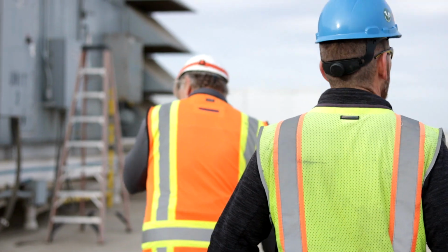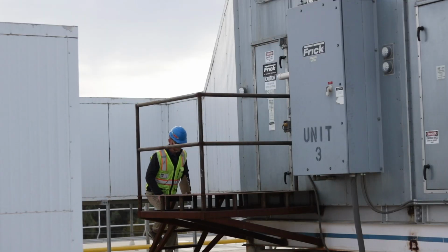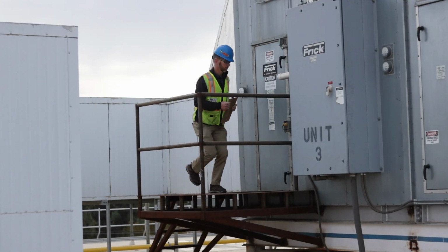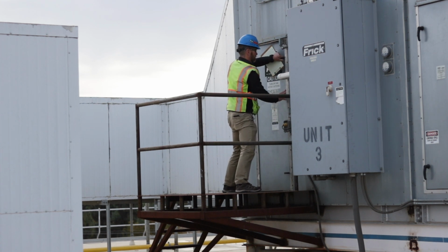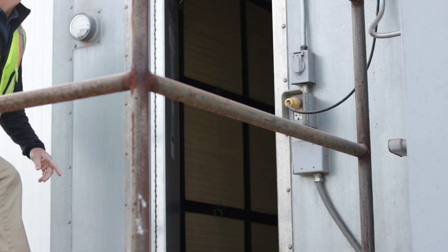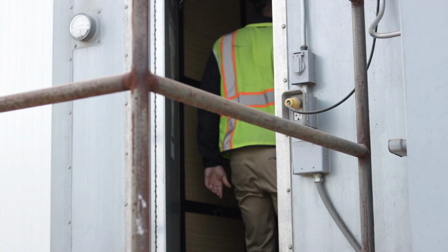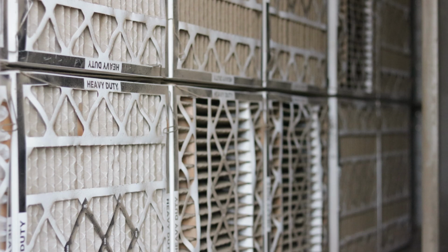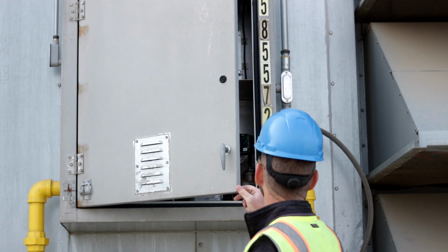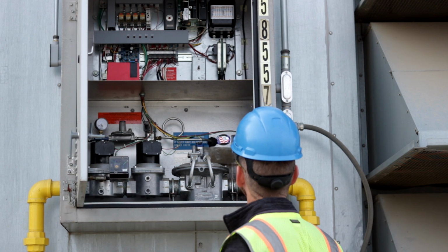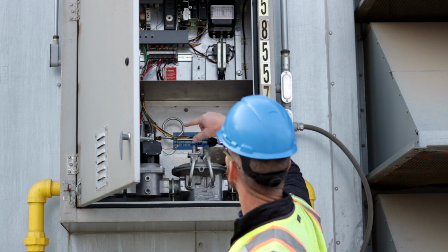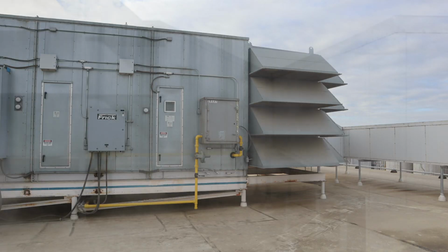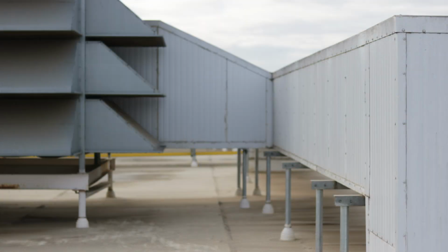Air handling units are a unique type of air cooling evaporator that are typically installed on a roof, but can also be ground mounted. Air handling units have a finned coil like other air cooling evaporators. What makes an air handling unit unique is that the unit will have other sections to handle the air for a specific purpose. For example, in addition to the cooling coil, an air handling unit might also have a heating coil, a humidifier, a filter bank, and a makeup air damper. Air handling units are employed in situations where precise air quality is required.